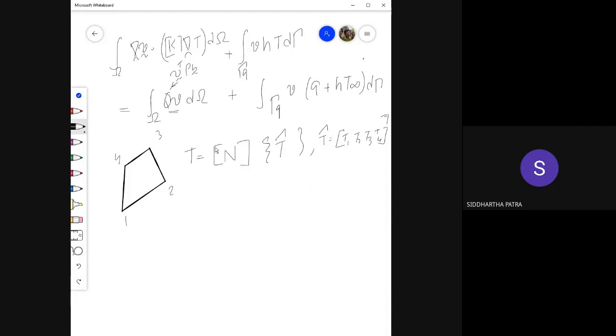these are. So what you do next is you need to calculate the gradient of the shape functions with respect to the natural coordinates. From that you need to get the Jacobian, and from the Jacobian you need to get the gradient of the shape functions with respect to the physical coordinates. Once you have done this, you can get the B matrix from it, and the B matrix is going to be quite different from the